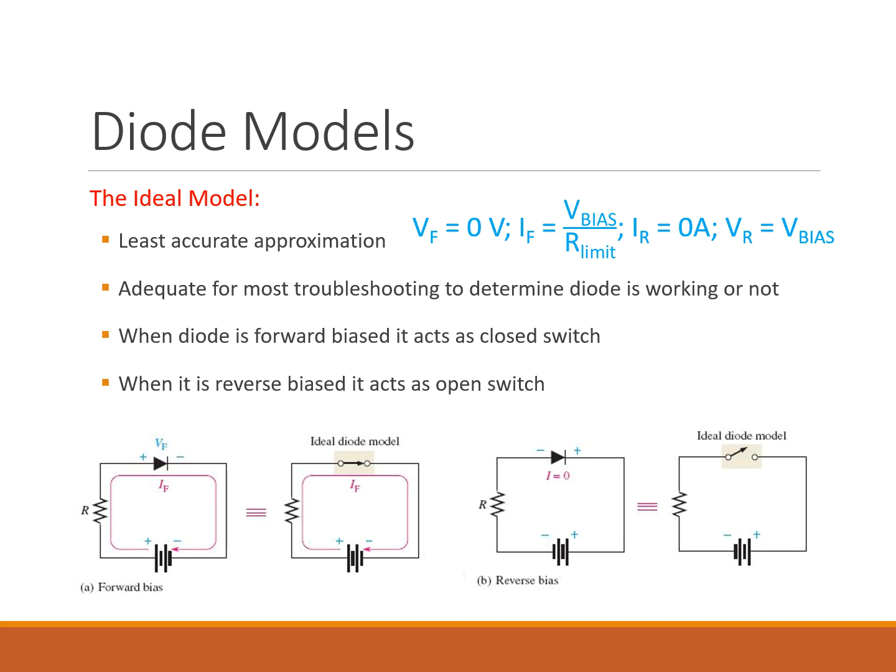Well, this ideal model helps engineers quickly tell if a diode is working or not, and it's great for troubleshooting, lab simulations, learning fundamentals, basic stuff like that. So a recap, looking at the diagram: in forward bias, current flows freely. In reverse bias, the path is completely blocked. So no threshold voltage, no internal resistance, just on or off.